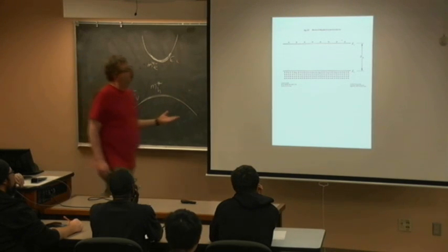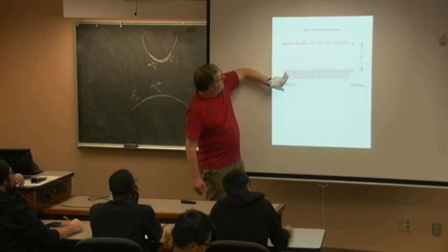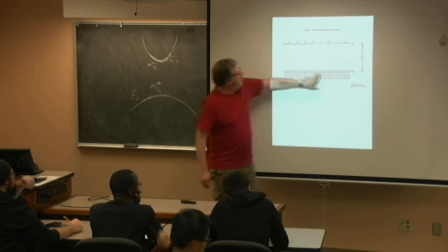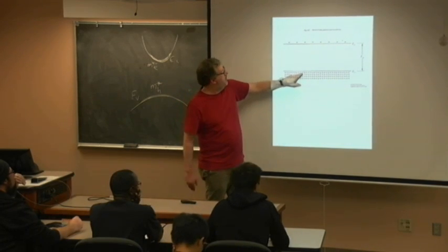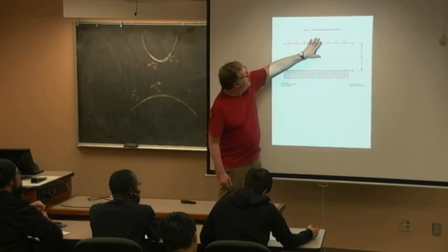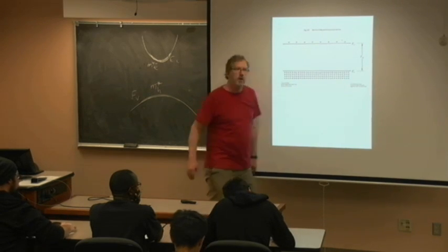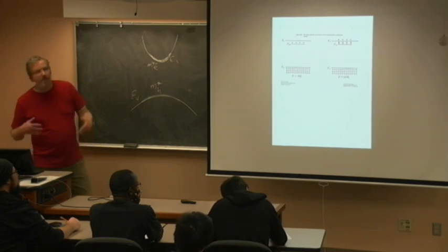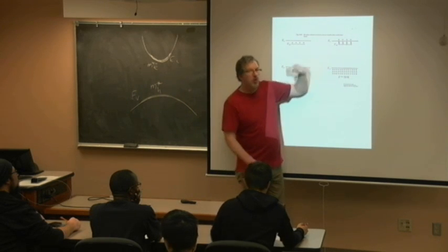So I start off with the forbidden band gap, and maybe I got a few parked cars on the first floor and a few up in the 7th, but how did these get here? These ionized, right? There's some thermal energy, and so these jumped. So this is intrinsic material, where the electron hole pairs are an equal quantity, because every one of these is a thermal ionization event. But if I did my doping thing, I introduced that substitutional dopant, and I chose my dopant well.